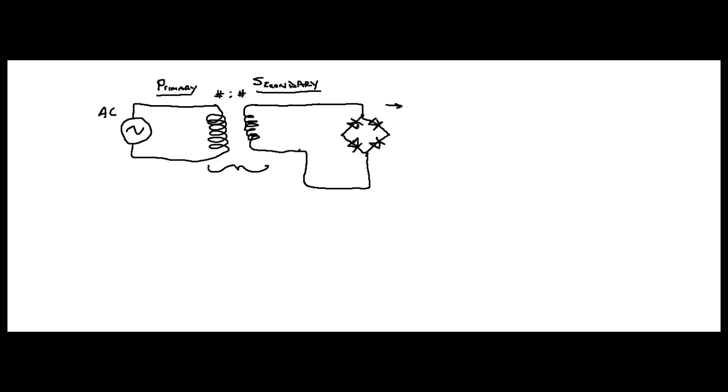Got it? Let me draw that one just a little better here for you. I'll fill them in here for you. There you go. Let's bring this one over here like this. Make it look like a real arrow. There you go. Now, so you understand, right? This your transformer comes to this bridge. This side is going to come out. We're going to go through a load resistor. Call this one R sub L, right? Now, generally this goes to ground, and this other side of your bridge goes to ground, right?